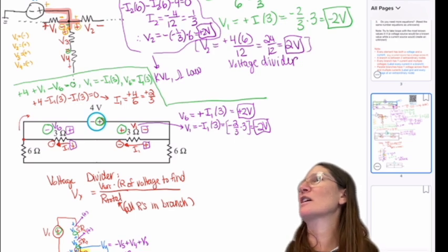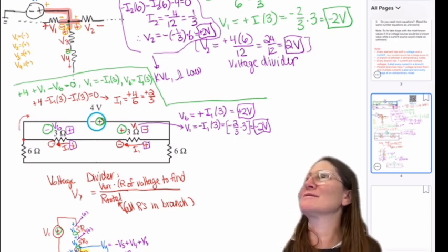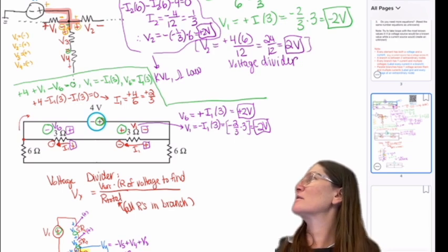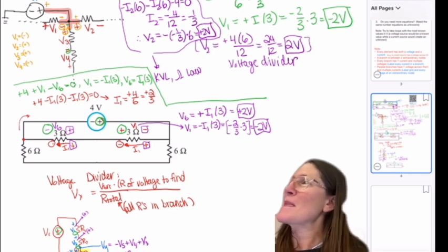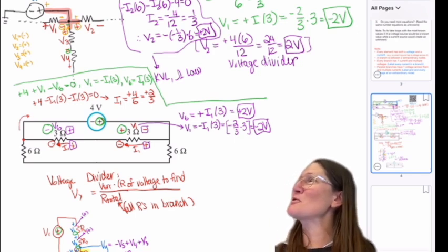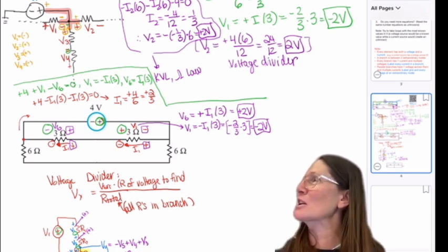So even if we're given a problem and it says negative, we're still assuming it's flowing out of the positive side? Yeah. That makes sense, because that way it always stays consistent. Okay. If we do get a negative, do we want to swap our notation to show it, or no? Nope, keep it there. If you don't like the negative number, just put a variable there and then substitute it in the math later. Okay.